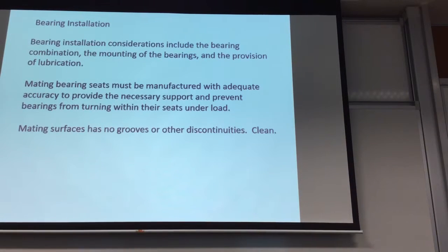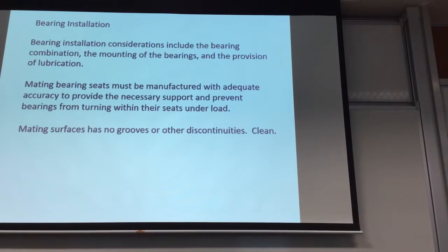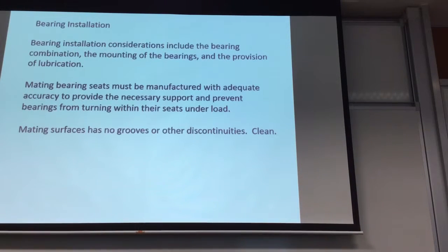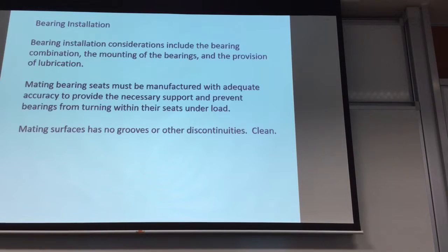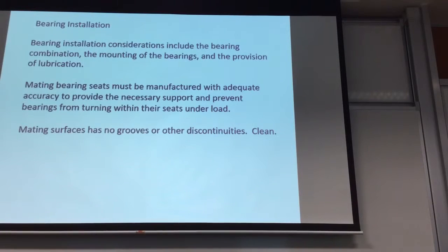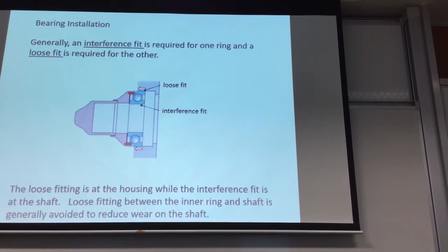What you must remember is that when you assemble your bearings, you need accuracy in dimensioning because you need to prevent the bearings from turning unnecessarily within the housing or your frame. Mating surfaces must be clean and should not have any discontinuities.